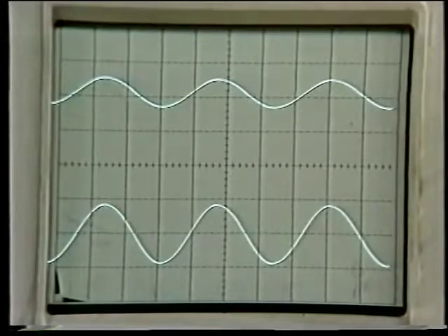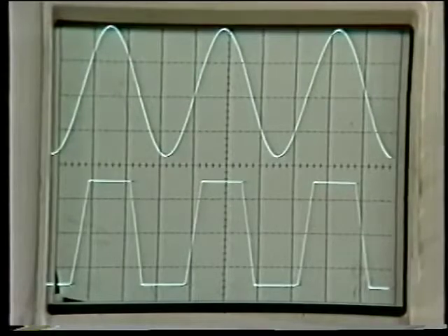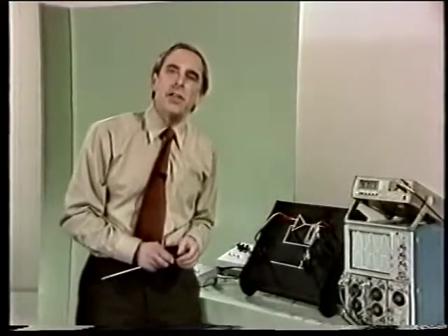So I'll do the same as before. I'll increase the input so as to get the same output level as I got without feedback. Well, the distortion is back again. What's happening is that we're getting saturation.